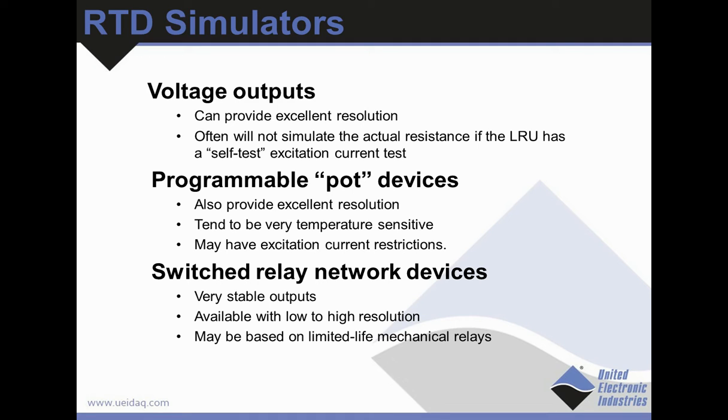It's basically a bunch of very high precision resistors that get switched in with low resistance relays. It has very stable outputs. Depending on how many switches and resistors you want to put in, you can make the resolution arbitrarily large. Some devices using mechanical relays may have a life issue, but these days there are such good FET-based relays out there, with less than 1/4 of an ohm on resistance, that will probably last forever.